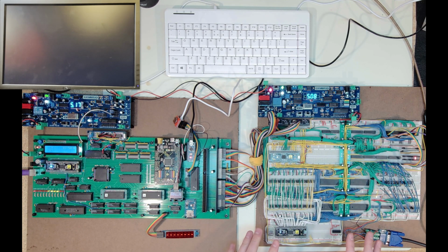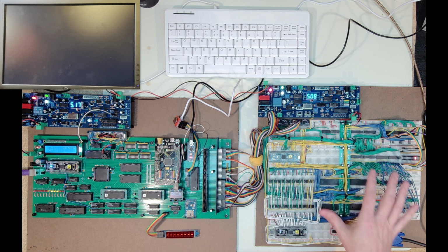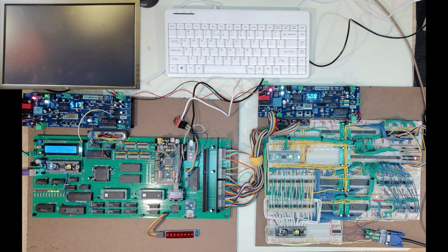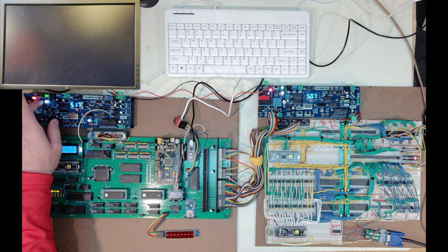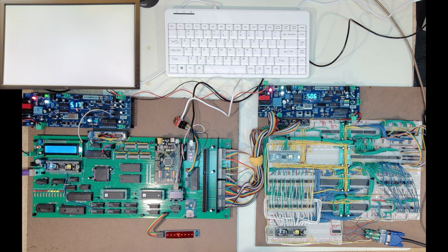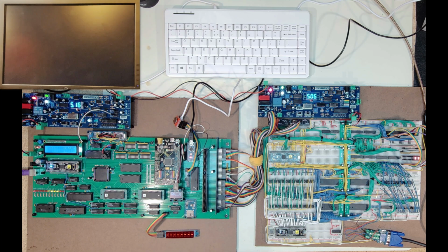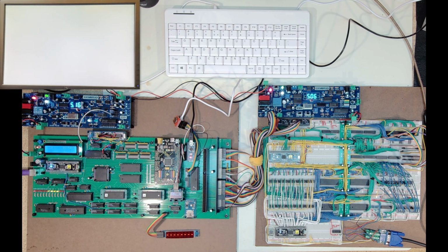This has given me enough indication that I think I can probably order, or I'm close to ordering, maybe a PCB version of this, so that I can do things like quickly swap out the ICs with AC versions instead of HC versions, and maybe do some other things. And I am finding a lot of value in this little bar graph output, so I'm probably going to take away this temporary wiring and put in more of a laid down wiring, just because that is kind of handy. As I do a reset, I can see where I'm waiting for VSync. I can see which frame is output. I can see which segment I'm currently working in within a frame. And that's all pretty handy.